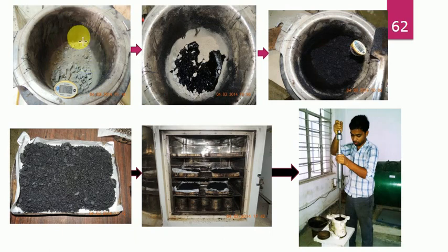Then after heating up the aggregate, you have to put it in a pan where you put the bitumen, and again you start mixing. Mixing the aggregate and binder in the laboratory mixer at the appropriate mixing temperature is mandatory, depending on the type and grade of the binder used, so that the aggregates are fully coated with the binder.